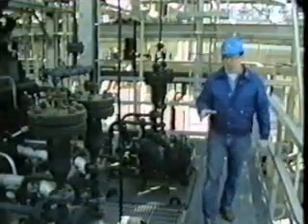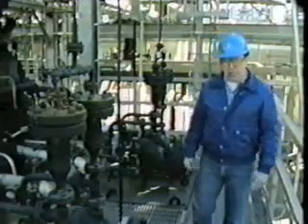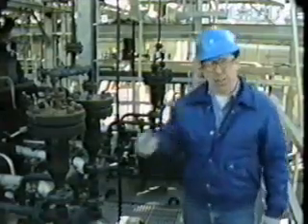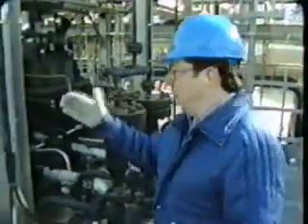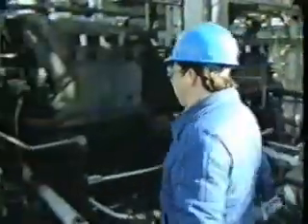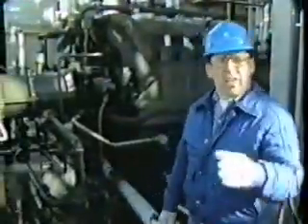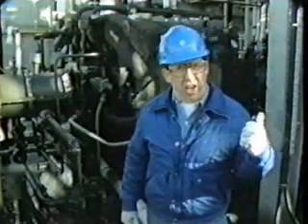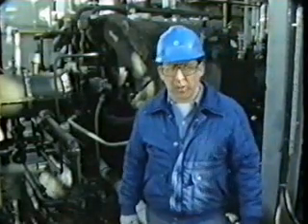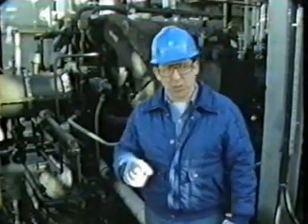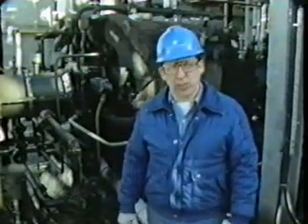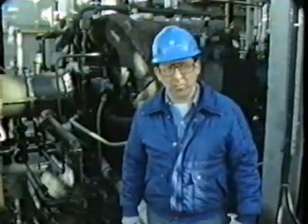There are several factors that affect performance of the compressor. For example, varying the speed of the compressor will vary the volume of gas moving through it. Recycling gas back to the suction side will also alter the performance characteristics of the compressor. So in this way, operators can achieve different results for the compressor.